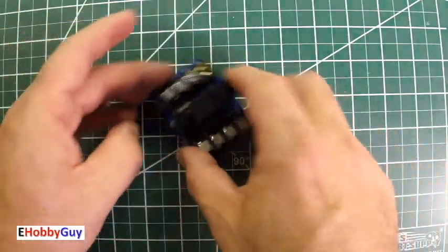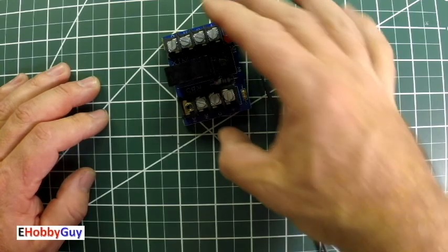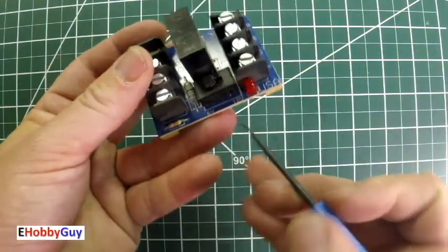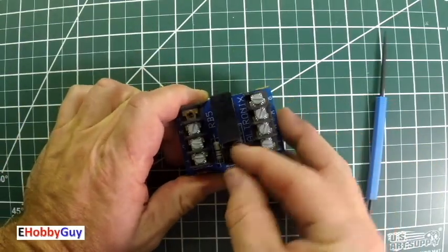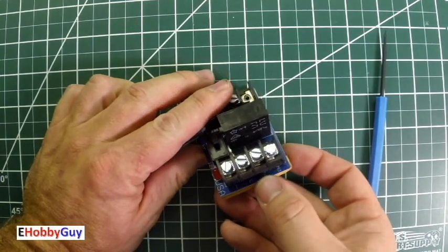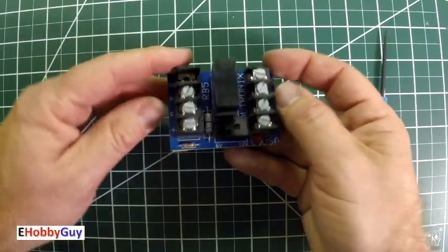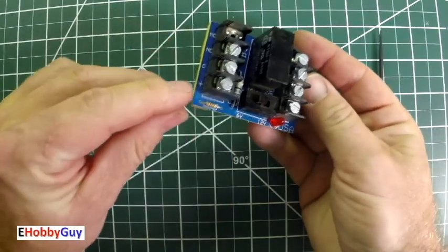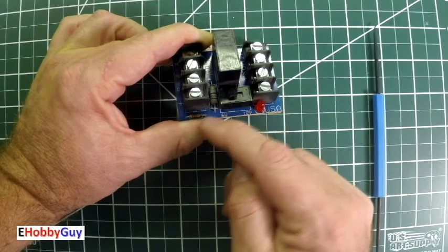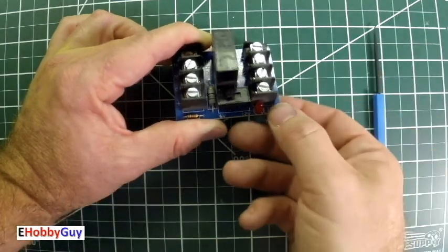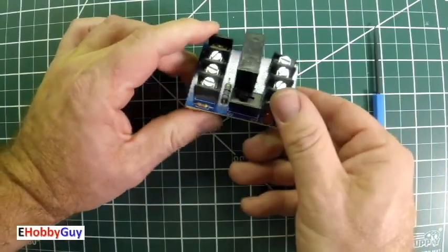Another type that is often used is really referred to as a module type. This is a more versatile one where it's got two voltages, a 6 volt and a 12 volt, and you can select which voltage you want with this switch. So you can see here it's common, normally open, normally closed. Common, normally open, normally closed. So this is a double pole, double throw. Positive here, negative here. The resistors are just creating the voltage divider for the 6 volt, 12 volt selection. And the red LED comes on when this relay becomes active.